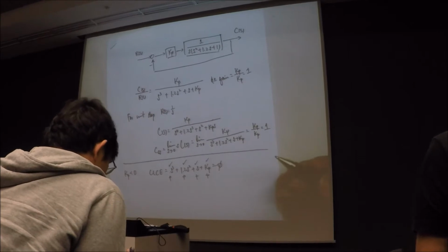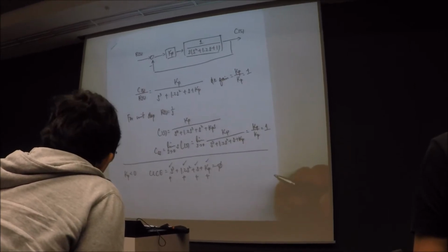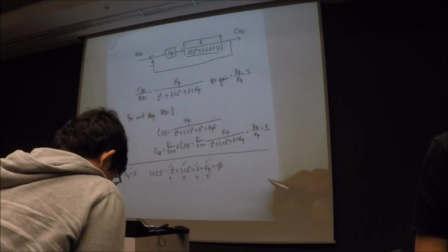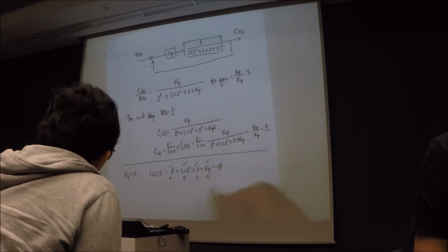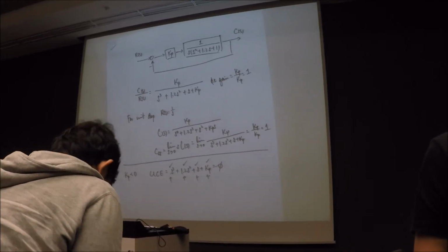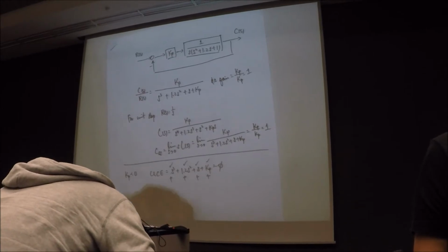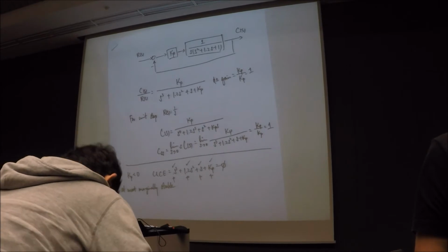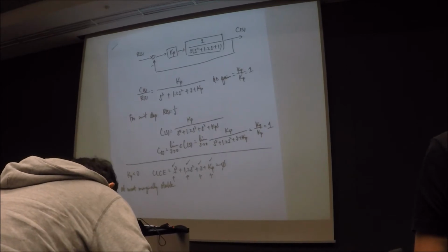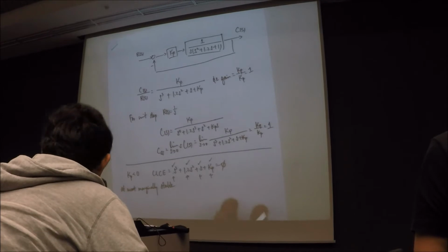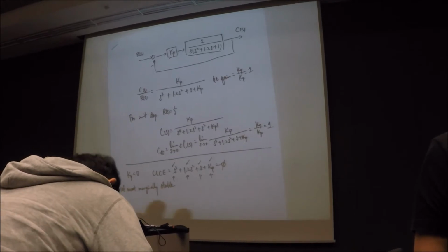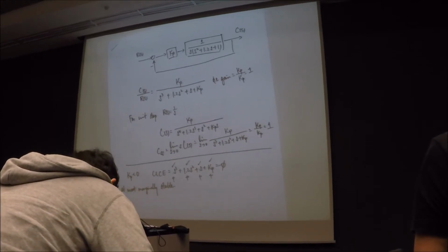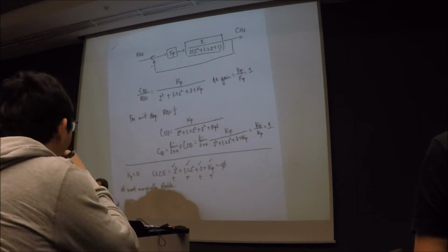So what is the effect on the stability of the system of a negative value of Kp? That means when Kp is negative, what can we say? I taught you, right? The system is at most marginally stable. Alright? We mentioned that when you have one of the coefficients missing or negative, in this case you can actually say that the system is unstable.